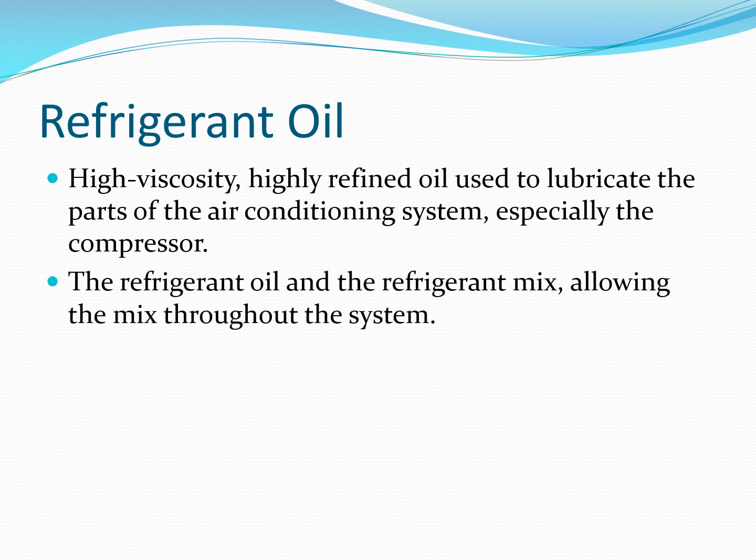The refrigerant oil and the refrigerant need to be able to mix. That's very important here. As we saw in the chart before, we have different refrigerants that we are using in automobiles. Now, I doubt you're going to be running into very much R12 systems out there. Most of those are gone, and if you have an older vehicle, it's very likely been converted to one of the new refrigerants.